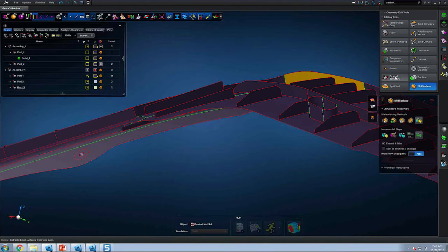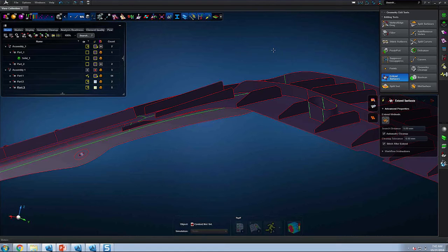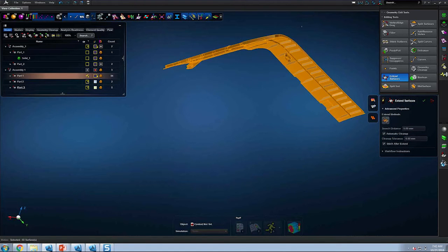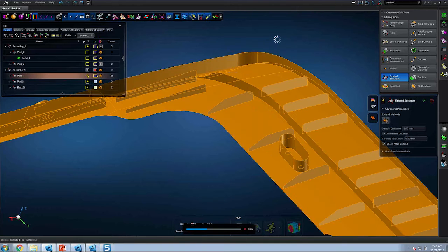A lot of these free edges could be issues to complete, but here let's go ahead and extend some of these free edges. And in a moment, if there's a free edge on another free edge, or a free edge on a face, the application will consolidate those. So now you have one, congruency across these faces, and two, instead of 54 individual mid-surfaces, you now have that reduced to, I believe, 1 or 2 mid-surfaces.